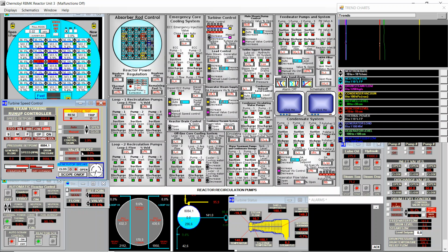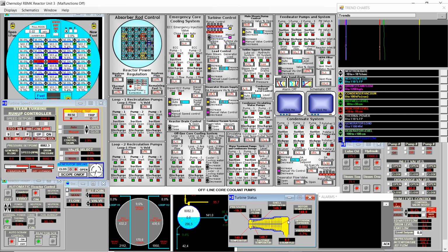We cannot just close to 0 the valve, because this will alter a lot the shell and rotor differential temperature, and then we'll have a differential expansion too high and the vibration will be very high. So I will start closing the valve slowly while looking at the temperature of the shell and the rotor.